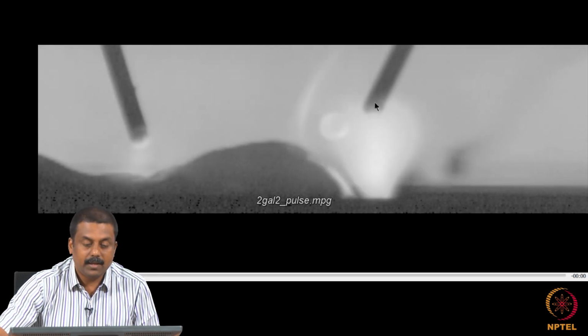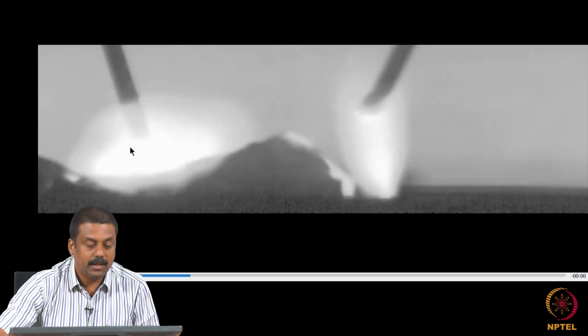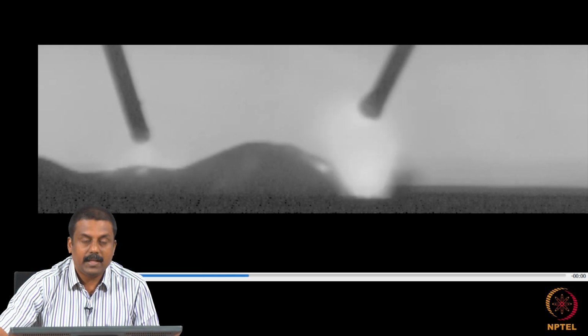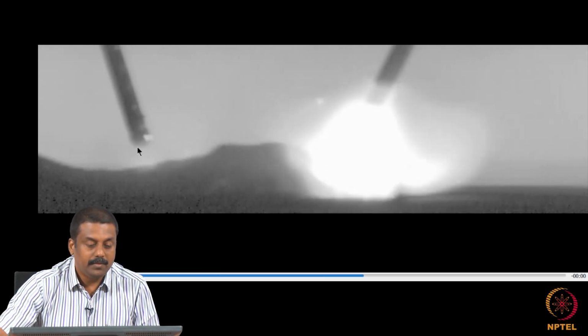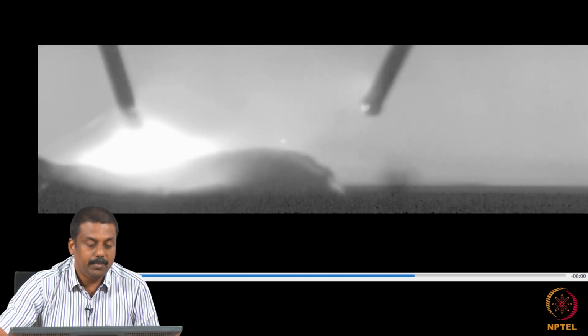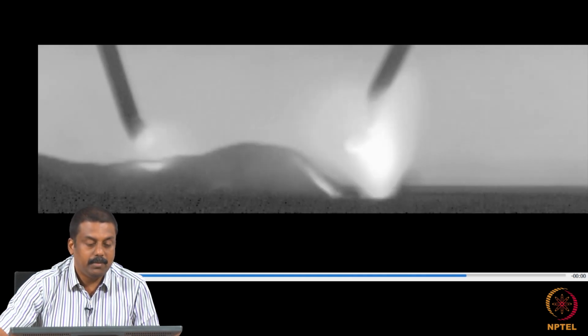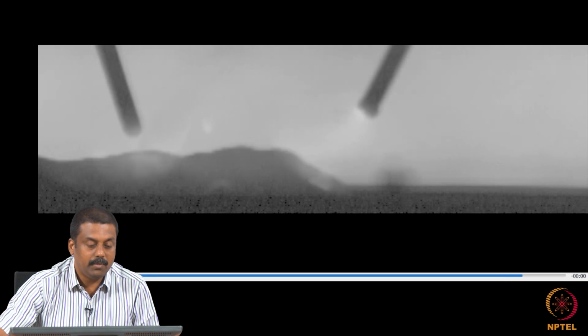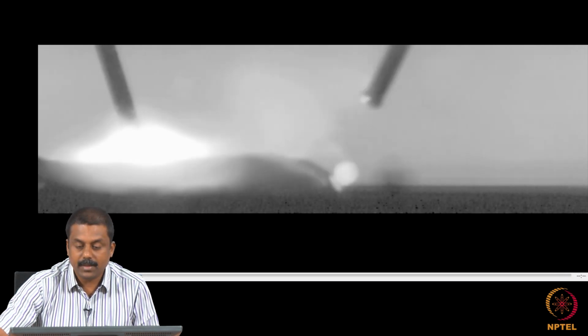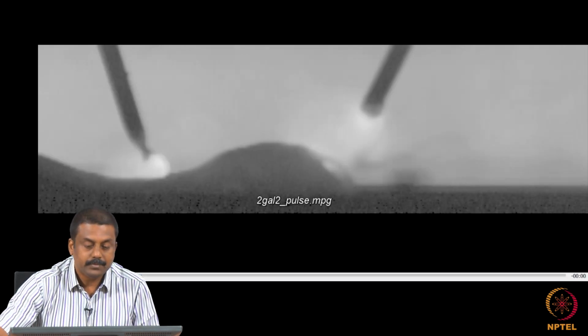And in this case, because we do not maintain a current higher than the mean current as in a conventional GMAW process, we increase the current only during the pulsing period, and then during the background period we maintain a very small background arc, as you may see in this video.